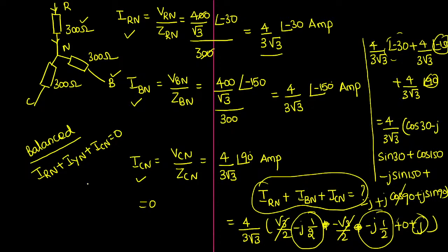So in case of a balanced system, in star connection basically we will have one more line, called the neutral line. This neutral line is not required when your system is balanced, because in a balanced system, the resultant of the 3-phase currents is 0. So why should we carry 0 ampere using one more line? It is 0 already. So only when your system is unbalanced, the neutral line will exist with the star connection. I hope now you got the clear conclusion about the circuits.